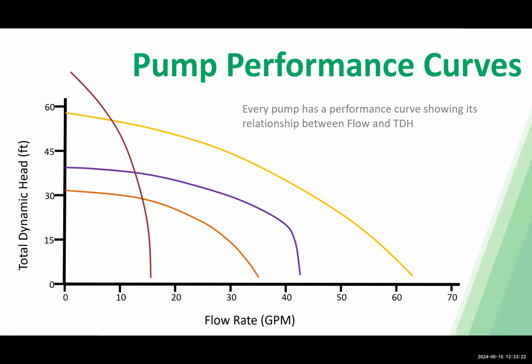Yes, and I actually do get into this a little bit more later in the slides, but real quick, just to answer the question, you want to operate in the center of the curve if possible. If you're operating too far to the left of the curve, that pump is doing a whole lot more work, or it's essentially losing efficiency in that end. Whereas if you're operating to the right of the curve, that pump is drawing more power and is reducing its life. So you kind of want to operate in the center. And I have a little bit of a graphic to show that later in these slides. Okay, perfect.